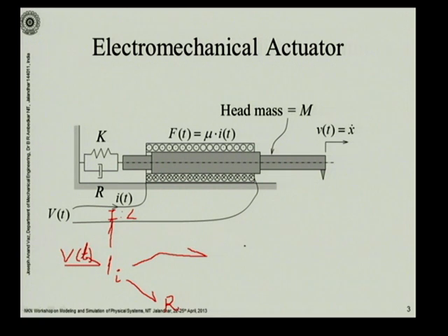So let's say, what should you use for the electromechanical effect? A gyrator. Why? Because the relationship has been provided here. You are going to have a relationship between current and effort, which is force. So here you will have a gyrator relationship, and it will produce an output.